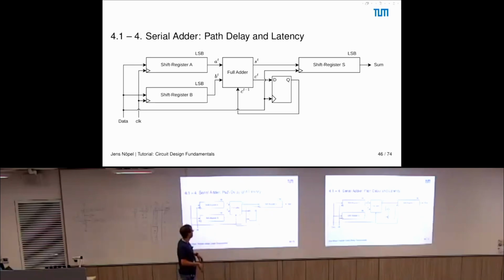As soon as you have done this, you shift those two by one position. Now the bit next to the LSB is at the LSB position. You take that, do the addition, shift in the result here, update the carry, which is then used for the next one as a carry in, and so on. And you do that until you've calculated all the 16 bits.